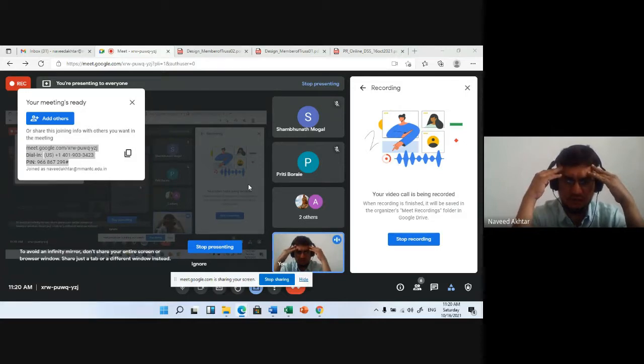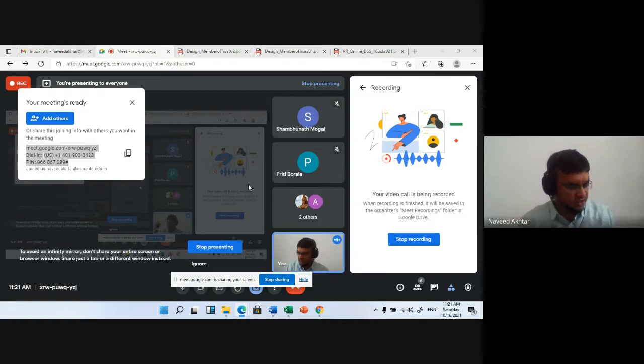That also we have completed, and based on that you have designed the rafter, that is the compression member of the truss, the strut, that is also a compression member of the truss, the tie member, the bottom tie, which is under tension loading, and the ceiling main tie, that is a tension member, you have designed.